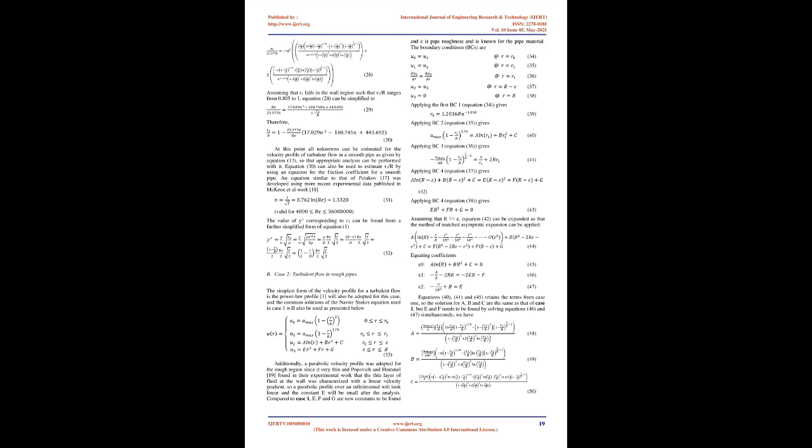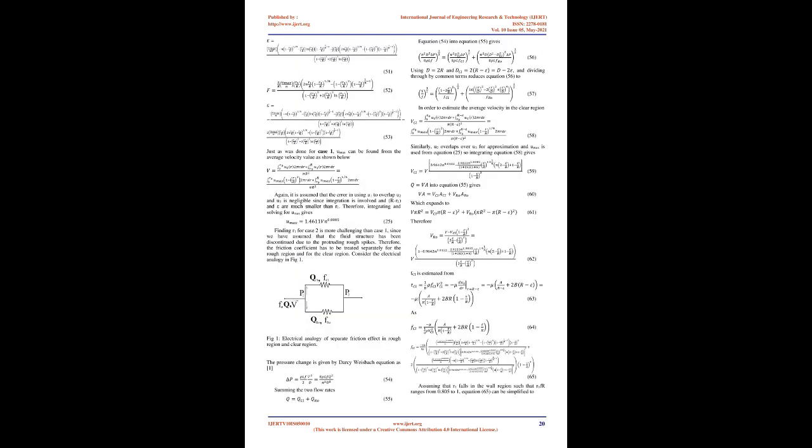Discussion. The results in Table 1 and Table 2 show that R1 is a separation between two flow regions. R1 clearly separates the outer region from the wall region. Table 1 shows that for turbulent flows in smooth pipes, the normalized distance from the wall at which the boundary between the two regions occurs is always greater than 30 and increases logarithmically with increase in Reynolds number. Turbulent flow in a smooth pipe is therefore expected to have both a viscous sublayer and a buffer zone.